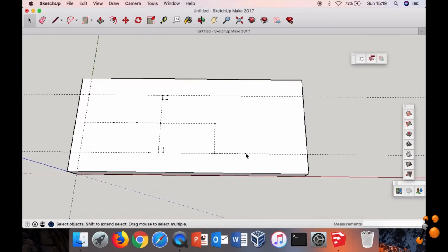I would like not to stop my device directly here, so maybe we should add a little bit of distance, like 3 millimeter. And don't forget that we also have a thickness of the wall on this side. So we make it a little bit longer so we can put it until here.